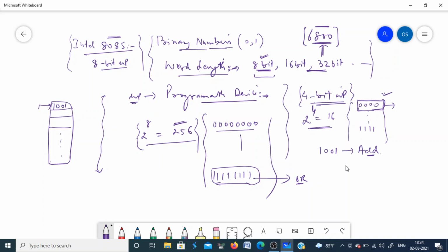So the machine codes or machine language for different microprocessors are not in general compatible. That is why, whenever you start with any microprocessor, the first thing you must do is go to the user manual of this IC, which lists all the instructions which the microprocessor can do.